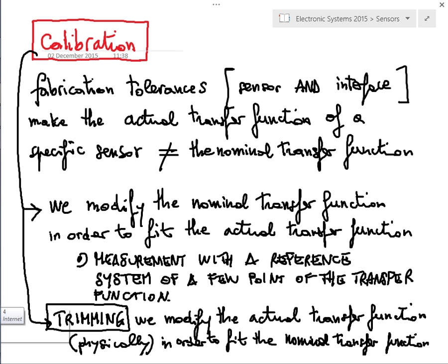The first step of calibration can be done in the fab, and typically by writing the coefficient in some ROM in the device, and it's a very common situation. But then there are also situations in which one must do a periodic recalibration, and in that case typically the calibration procedure is simpler and must be faster to perform.